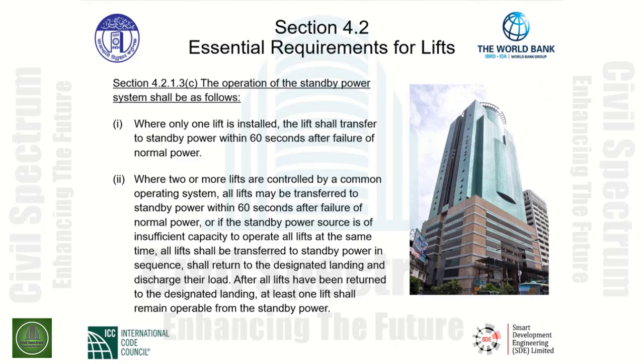Or, if the standby power source is of insufficient capacity to operate all lifts at the same time, all lifts shall be transferred to standby power in sequence, thus lessening the initial load on the system. After all lifts have been returned to the designated landing, at least one lift shall remain operable from the standby power.